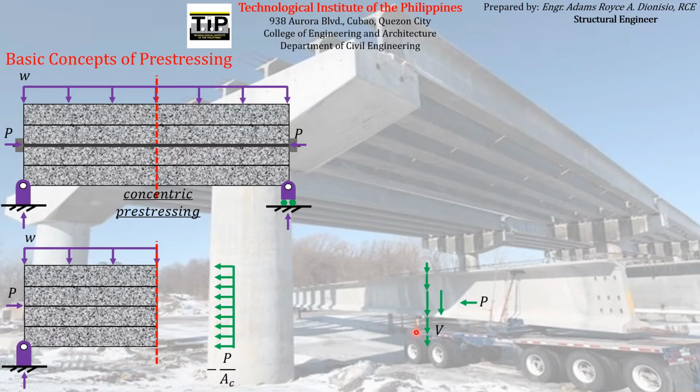Although again, we usually assume that these shear stresses are uniformly acting along the cross-sectional area, but has a magnitude of shear average or the average shear. But again, in real life, the shear stress acting on the cross-section of this concrete beam is not actually uniform but varying, with the maximum magnitude of the shear stress acting at the location of the centroid, and then it diminishes as you go to the top and bottom fibers, especially if this has a rectangular cross-section.